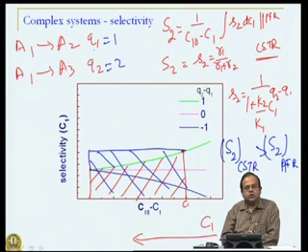But what happens when it comes to selectivity? The selectivity in a plug flow reactor is now worse than the CSTR, or CSTR is better than that in the plug flow reactor. What it implies is that for conversions PFRs may be desirable, but that does not guarantee high selectivity. For achieving high selectivity, CSTR is better than plug flow reactor. And why is this happening?